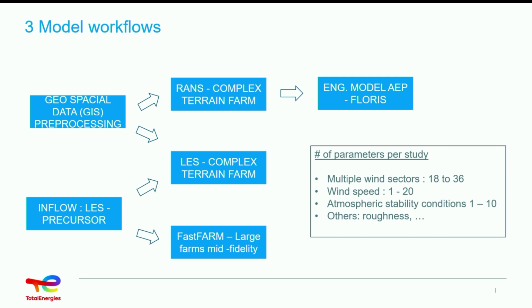Those workflows run on LES simulation to assess resource and yield on very large wind farms. So first we need geospatial information. Could be tricky, but it's a pre-processing step. And to have Reynolds-averaged computation capability in complex terrain to feed the engineering models I presented before.